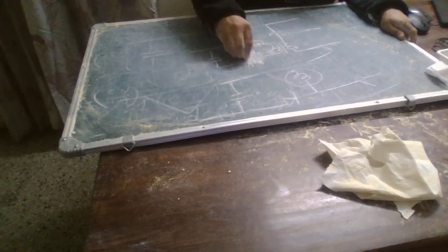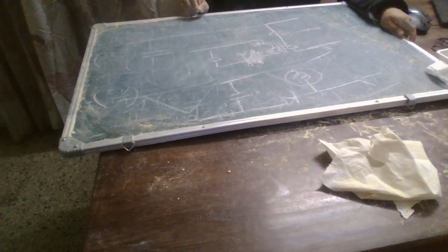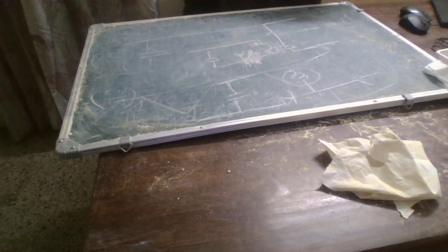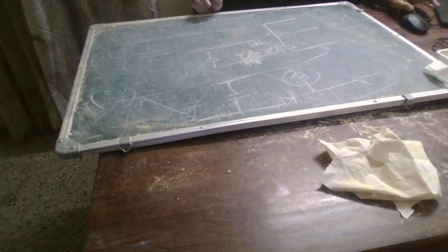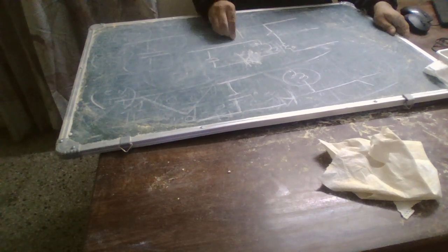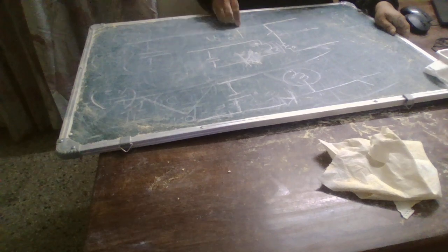So this is how a flyback converter can be very simply derived from the buck-boost converter, using the same inductor. The magnetic field inside the inductor in both cases, whether it's this single inductor, or 1:1, or even 1:n, is going to be the same.